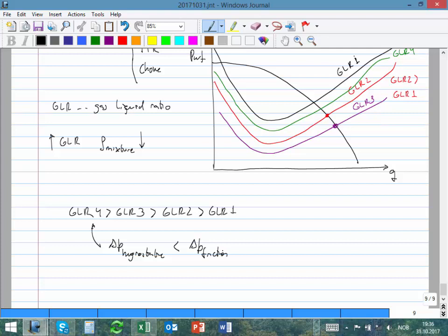All the gain from 1 to 3, you were gaining a lot by adding gas to the tubing. You were reducing quite a lot the density of the mixture. But after I went from GLR 3 to 4, that's the minimum that you can get, and then the friction starts making a big effect. So that's why you have a change of trend in the equilibrium point.